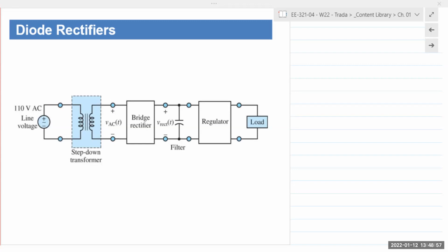Wattage. Also, the laptop adapters have a lot of other circuitry built into them. But for the most part, all the other chargers have to comply with the USB spec. The USB spec states that it cannot be more than 5 volts. Some of them go up to like 5.1 or 5.2 volts, but for the most part they are around 5 volts. So all USB devices can be charged with any kind of adapter. The only difference is how much current that adapter can supply.